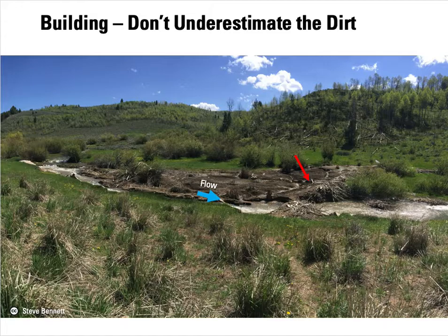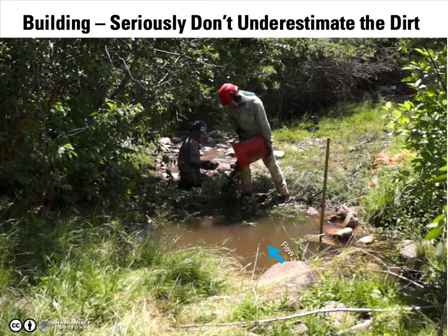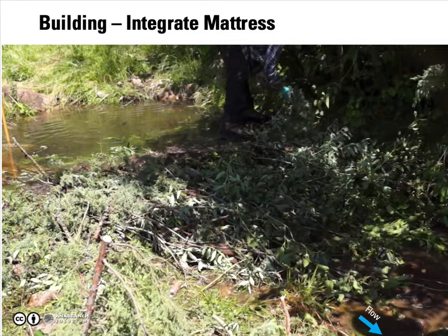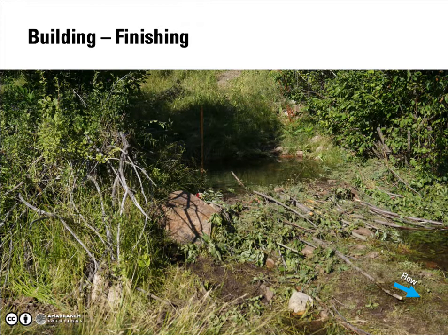And I can't stress how much dirt you need to pack here. This is a failed or breached natural beaver dam, and there's 3 to 4 feet of dirt packed on the front face of that particular dam to create that pond. So dirt. It can also be cobble or sod. Keep integrating your mattress as you go, and then finish it off at the crest elevation that you're shooting for.